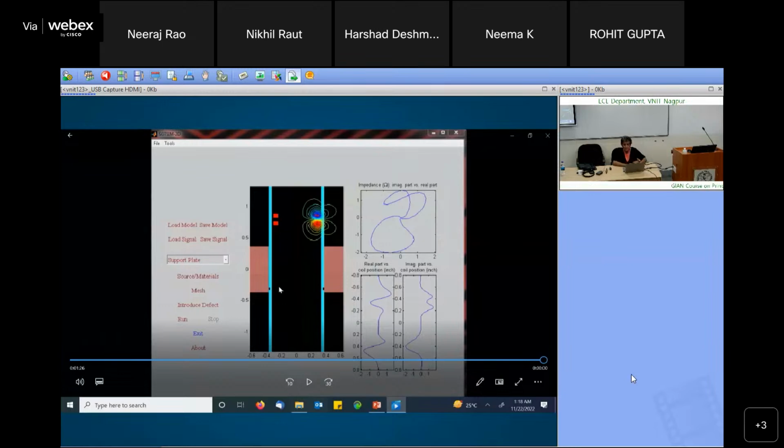We have done things like, the support structure doesn't have a defect, but what happens is, right now there is no space between the tube wall and the support structure, but in practice, there is a gap. And in that gap, all kinds of rust and deposits get deposited.